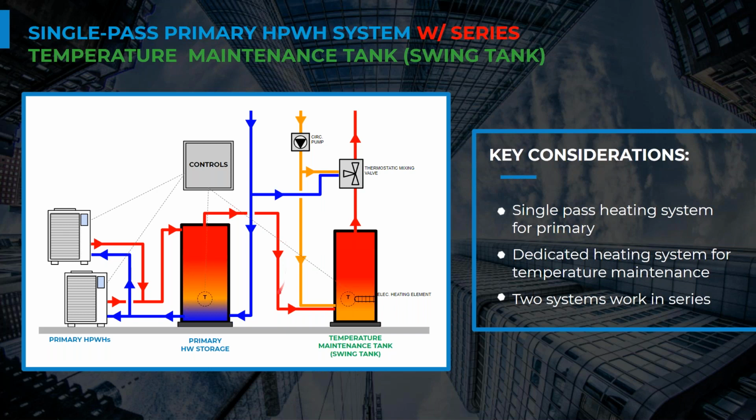And then the other thing you want to be aware of is, can I make that overheated water efficiently in my primary storage tank? We'll see that R410A and R134A are more impacted by higher outlet water temperatures. Their equipment COP will be significantly reduced if we make 150 degree water compared to if we make 130 degree water.